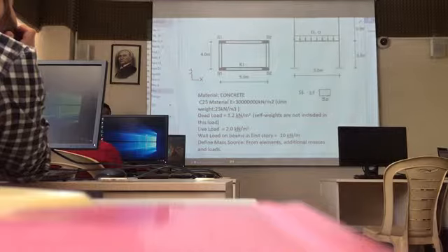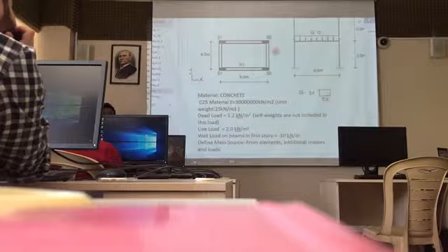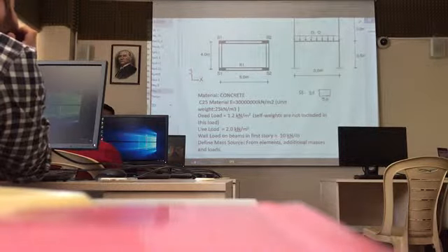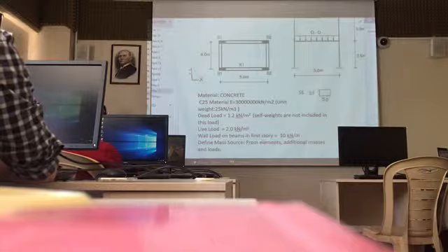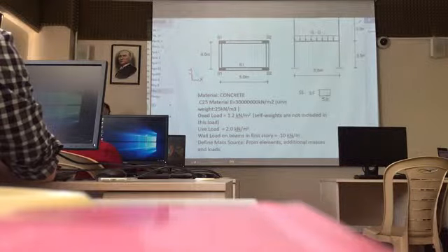It is always in the longitudinal axis of the column, okay? In the vertical direction for columns. For beams, in the horizontal direction. And what about the 3 local axis? Yes, we can find it using the right-hand rule from 1 and 2. Because 2 is always parallel to X, 1 is in the longitudinal direction, and using the right-hand rule, we can find the third axis.